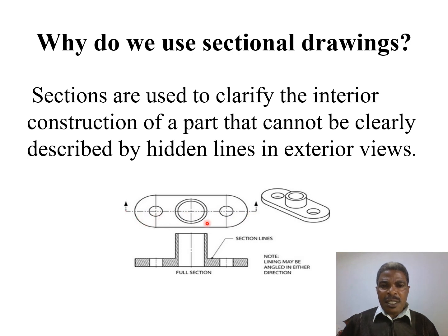The part that is very close to the observer is regarded as removed. So behind is left the part that is indicated with the arrows. This is an example of a front view for our object here, indicated with the hatching lines. The hatching lines are drawn at an inclination of 45 degrees from horizontal.